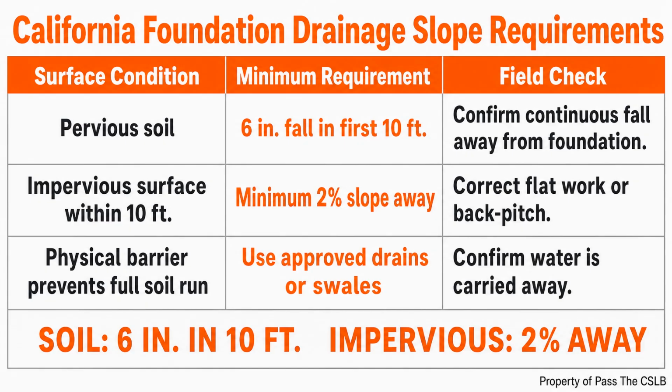Excavation also brings a separate safety responsibility. California occupational safety rules require a competent person for excavation inspections and for the oversight connected to structural ramps used for equipment access or egress. A competent person is not simply the most experienced person standing nearby. The person must be able to identify existing and predictable hazards, and the employer must give that person authority to take prompt corrective measures. Knowledge without authority is not enough. Authority without the ability to recognize the hazard is not enough.